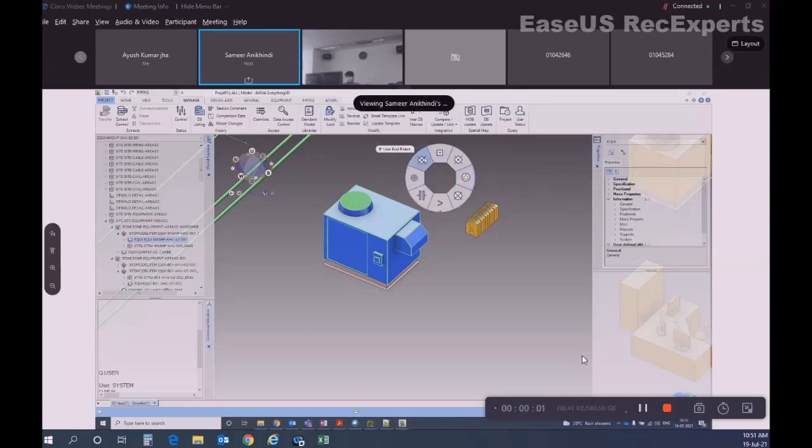So there are PLine snaps, PPoint snap, item snap, midpoint snap, node snap. These snaps will be discussed in the respective courses also, but for now you can understand these are various snaps. These are 3D snaps. If you go to the 6 o'clock position, you see more options here. In more options, there are 2D snaps also. 2D means edges, lines, surfaces, and all those things.